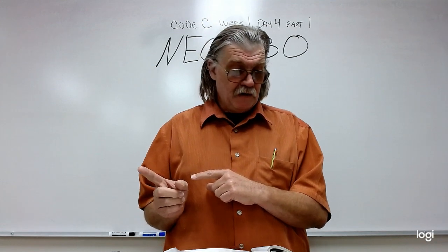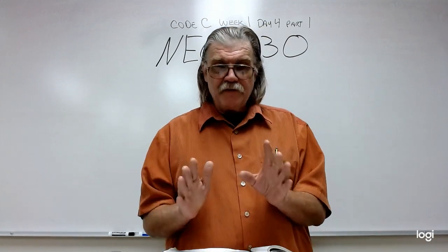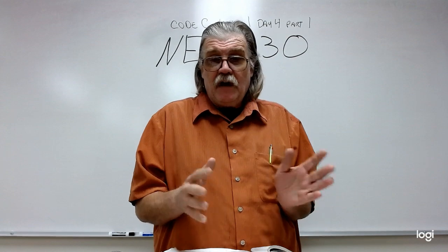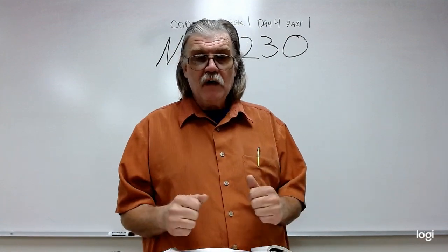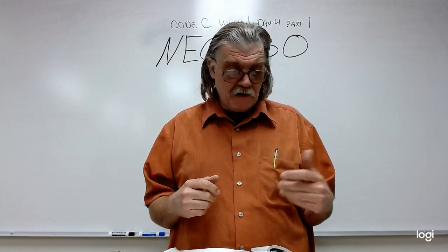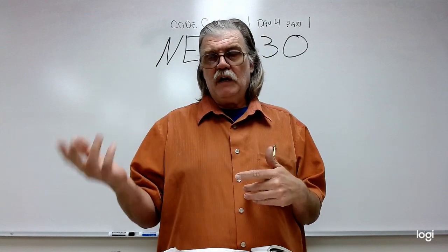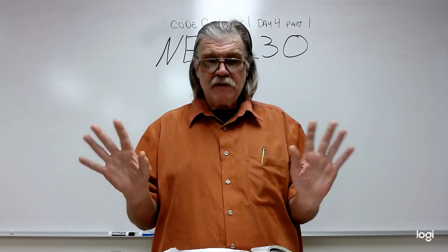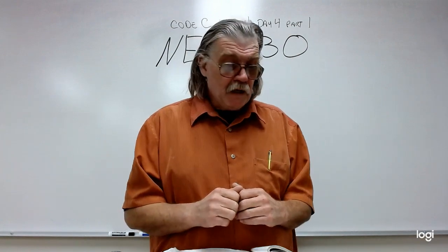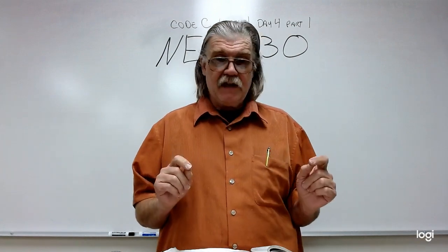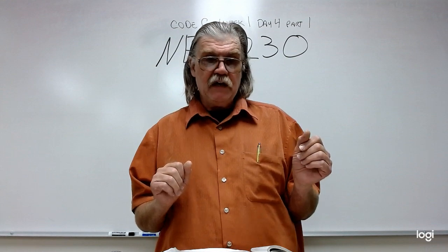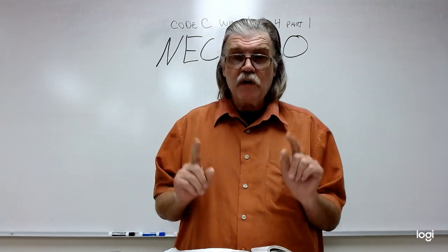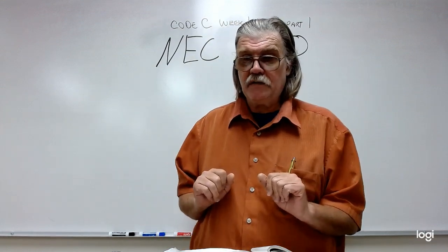Okay, that's definitely one thing we want to keep going, obviously, if you want to put out the fire. Other things we'd want to keep going as well would be emergency backup systems, like life support at hospitals, or just things like that. Because of that, it brings into play 230.72, the grouping of the disconnects, right?